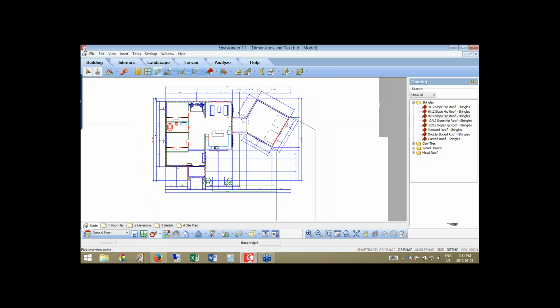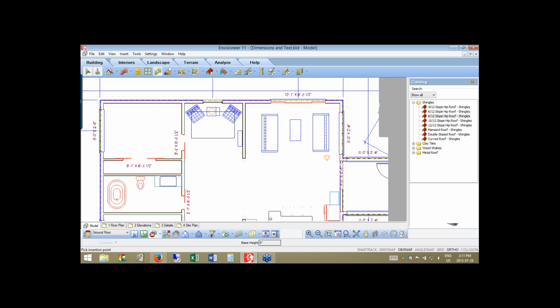With this particular tool, you draw a line through your model, and I'll just zoom in a little bit so we can see that happening. I'm going to draw a line through the model. I'm going to start here at this point and come all the way through to the other side of the building. And when I left-click and I cross and I'm creating that line, every wall that it crosses over, it's going to dimension to, and it's going to follow those same dimension rules that I told it to. So you can see that dimension line appear.